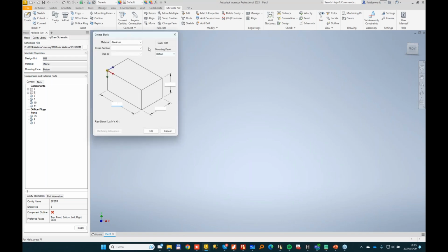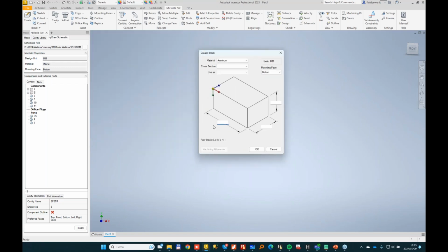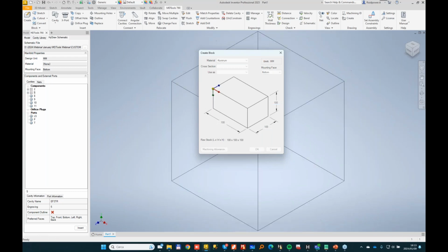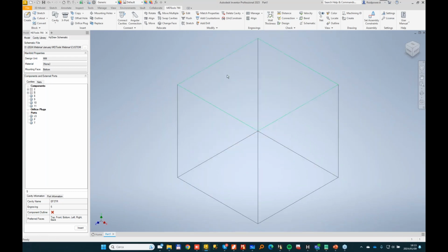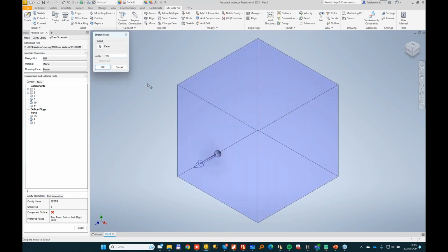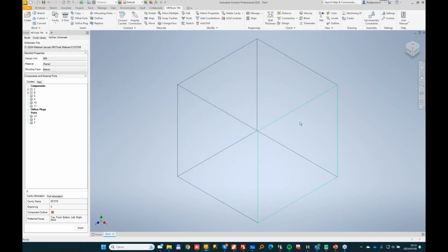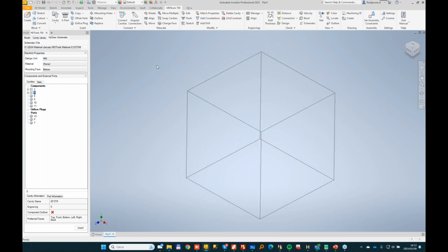This is not the case, so let me start my block, and I'll take maybe 100 by 100 by 100. Well, this is not really smart. Usually, if you start with a 100 bar, you may use 99 by 99 by 99. That's more. Because you want always to have squared faces. So normally, manufacturer will always remove a bit of material from all sides of the block.